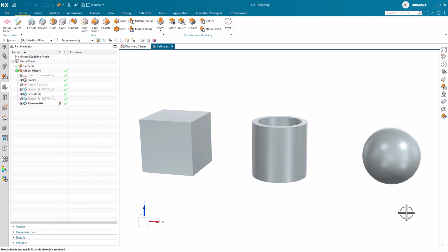Lattice structures are an important part of additive manufacturing. Essentially, they are repeated patterns that fill a volume or conform to a surface. They are particularly advantageous in applications where weight reduction, energy absorption, and tailored mechanical or thermal performance are crucial. The ability to design lattice structures with specific functionalities, combined with advancements in additive manufacturing, have made them an attractive choice for engineers and designers seeking innovative solutions.